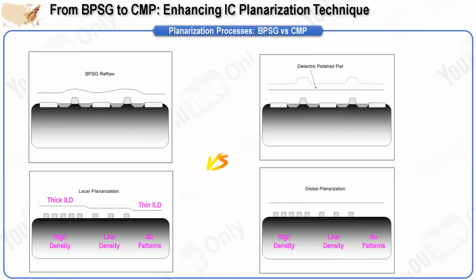The challenge arises during the subsequent lithography process, where the step height poses depth of focus problems during high-resolution lithography. Additionally, advancing optical lithography requires tools with high numerical apertures, NA, to print smaller features, but this comes at the cost of a reduced depth of focus window. Therefore, maintaining a flat film surface becomes critical for accurately focusing images across varying surface heights.